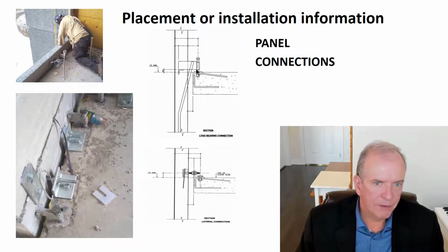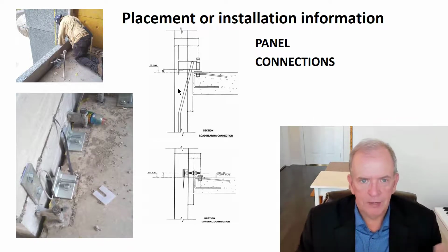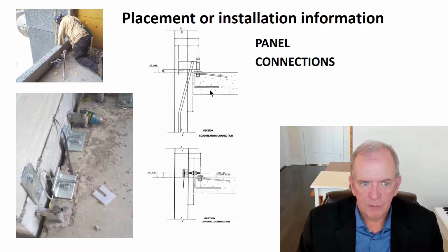So you might have to have embedded anchors put at those particular points in your slab. So you'd have to have these shop drawings done ahead of when your slabs are poured, so you make sure that the anchors are embedded in the slabs so that then they will line up and they can support the curtain walls, the precast curtain walls. So you start to see how these elements fit together. Like I have to have that information done and approved before I start pouring my slabs. If I don't have that, then I'm going to have a problem.